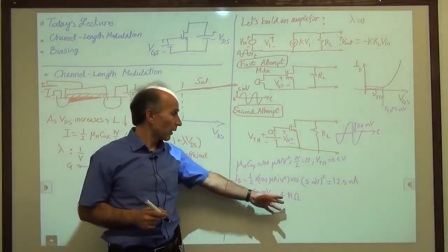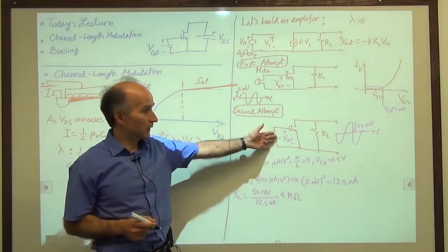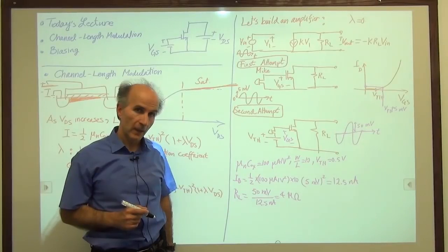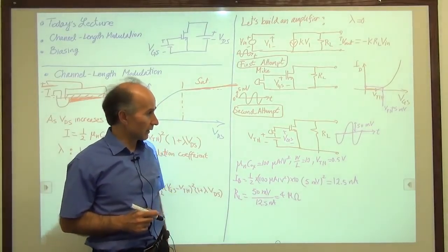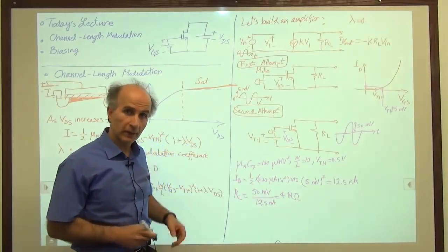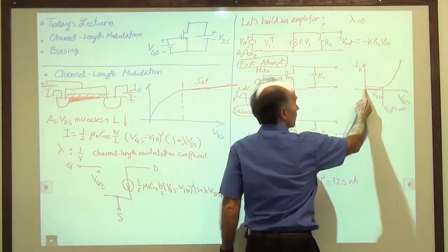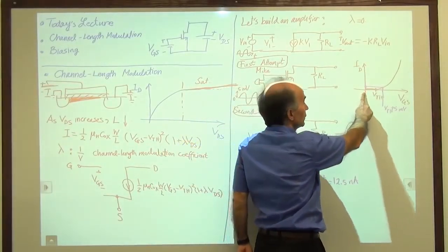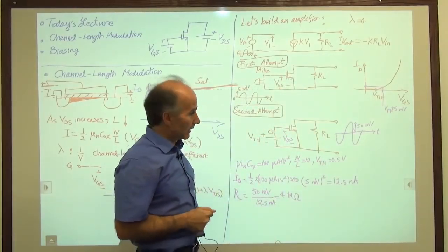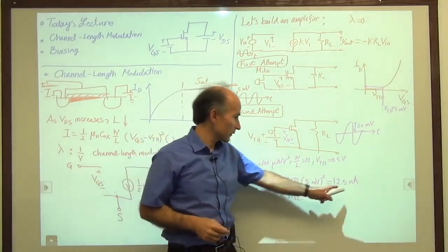So we could buy a 4 mega ohm resistor in discrete form, but we don't want to build an amplifier like that. That amplifier would not be very good. All right, so something is not quite right here. Even though we added a voltage, we brought the operating point from here, where the transistor was totally dead, to here, where the transistor is partially dead, right? So can I improve further so that I don't end up with such a small current here?